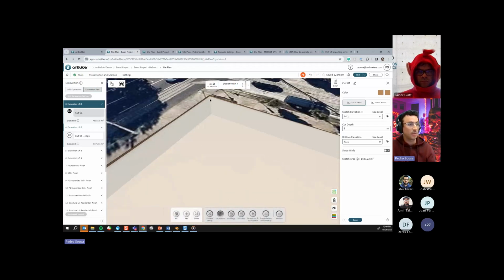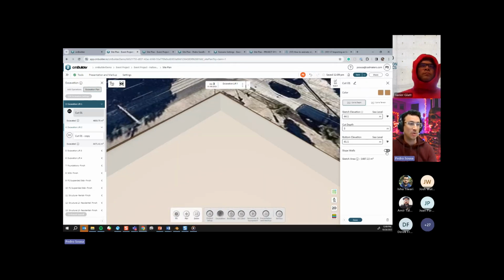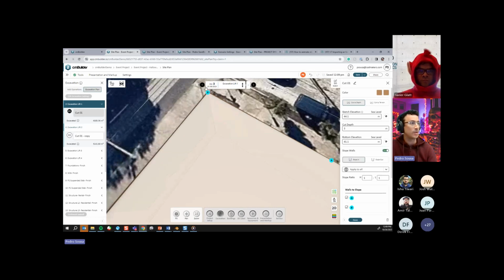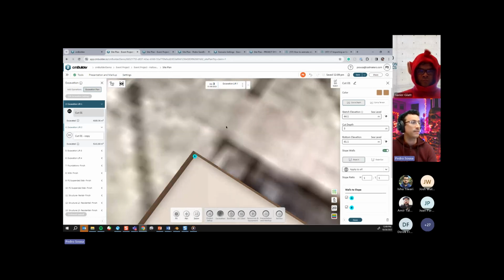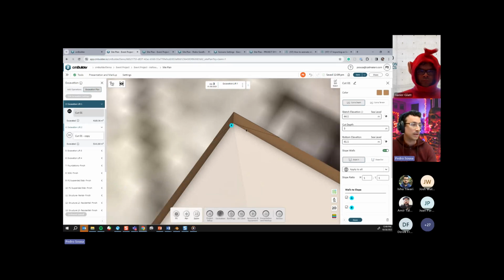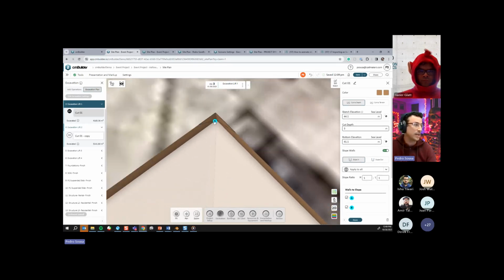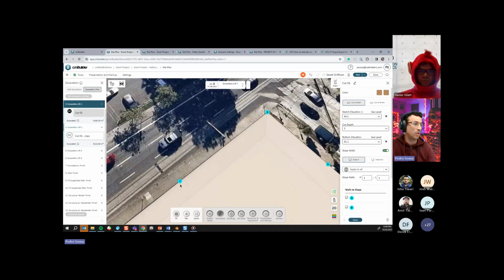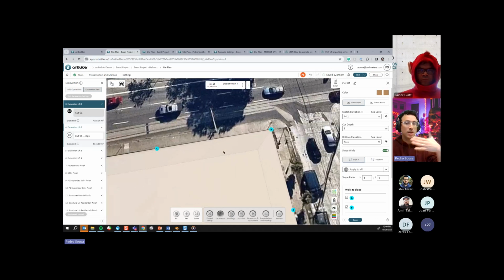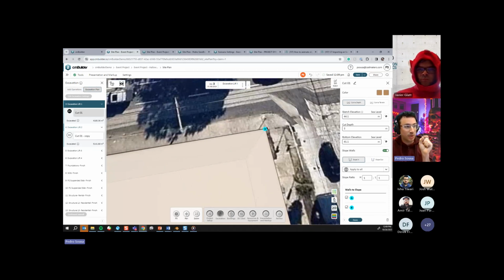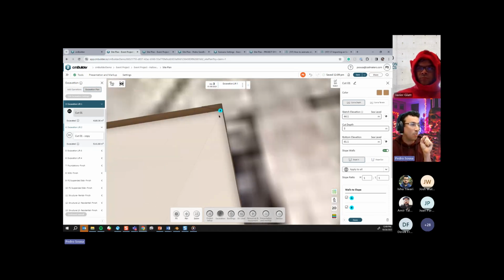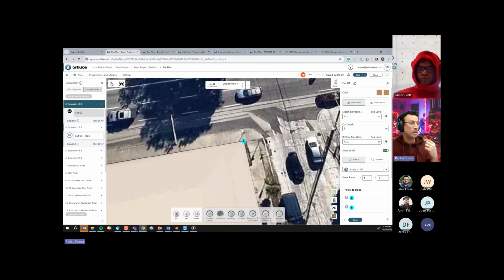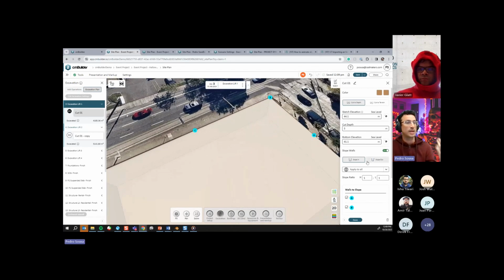Right now, it didn't create any problem, but if I slope my walls, you're going to notice that in here I have two more triangles being generated. And over here, there's a B wall, but also a C wall. So these are coplanar walls that you are working on. Because we created those two points too close to each other, there is a new wall over here being computed. So when you start creating your slopes, this might create a broken geometry or something that you're not expecting, right?